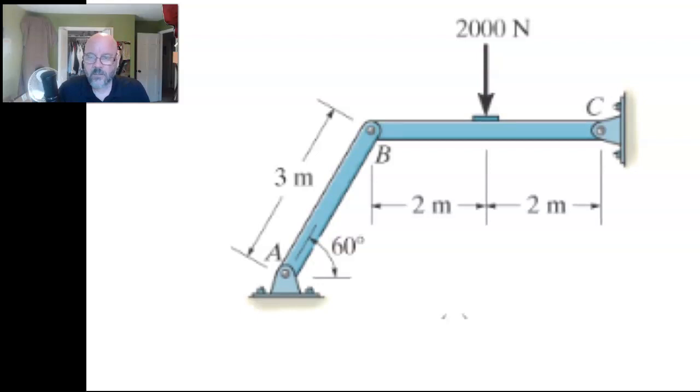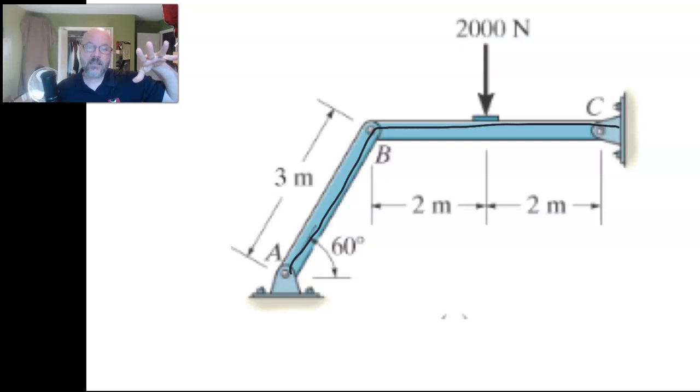All right, there we go. Okay, now I'm going to show you why in just a little bit, but realize that this is not one solid piece. And I kind of mentioned this once before. If it was one solid piece, what happens at C would actually be different than what we're going to have. Okay? And I'll show you how that works out because it's not intuitively obvious. All right, it's not intuitively obvious, but the reason that it's different is because that hinge pin will not transmit moment. Okay, so let me pull that off of there.